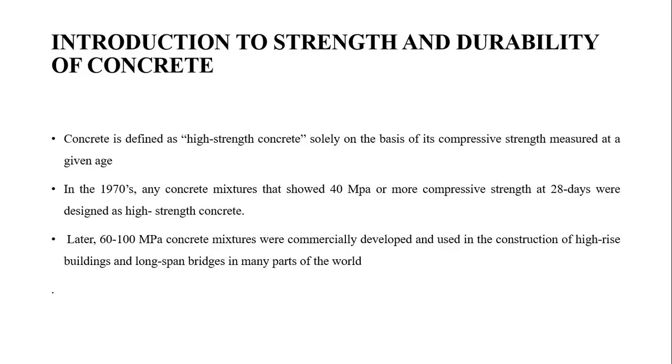though MPa is nothing but a unit of pressure, and which has the compressive strength at 28 days, it is designated as high strength concrete. And later 60 to 100 megapascal concrete mixtures were commercially developed, and they were used in construction of high-rise buildings and long span bridges in many parts of the world. So this covers the strength and durability of concrete.